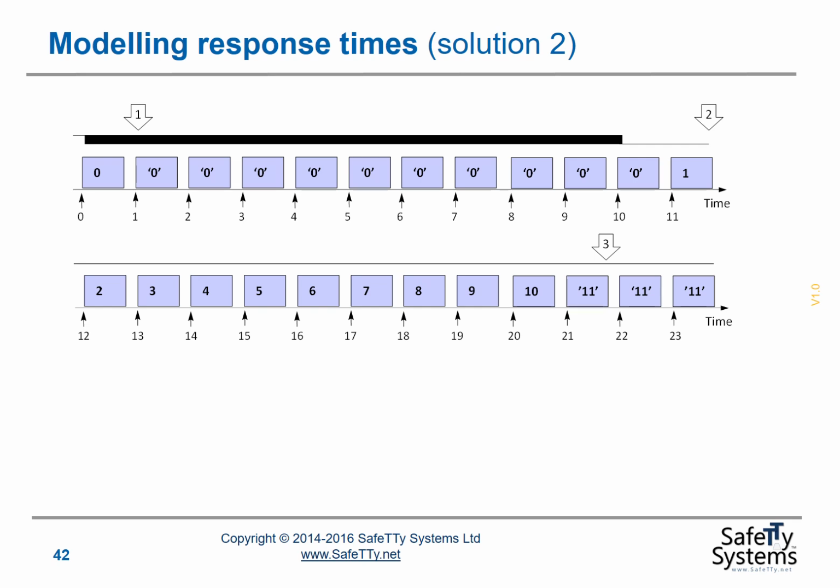So the switch bounces for 10 milliseconds. We start incrementing the count of how long the switch has been solidly pressed for in tick 11, which is indicated by the arrow 2. It then takes us until that count gets above 10 until we can set the global variable that indicates that the switch is pressed. So that means that we have a total time taken to do this of 21 milliseconds.